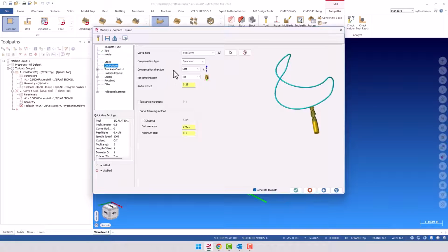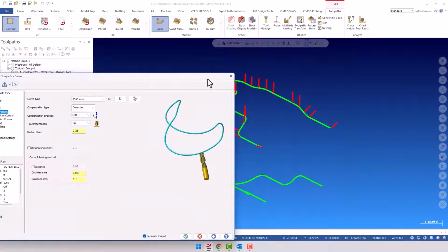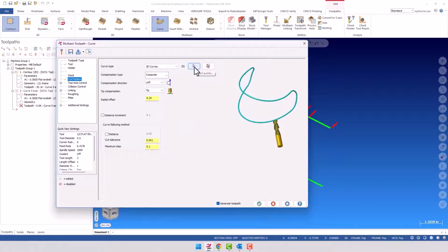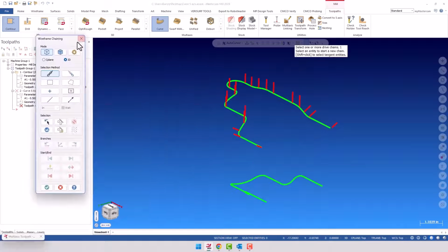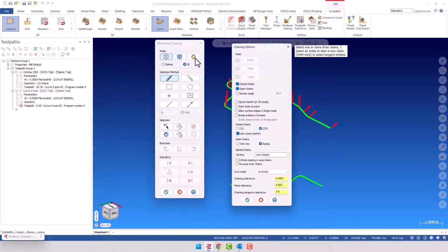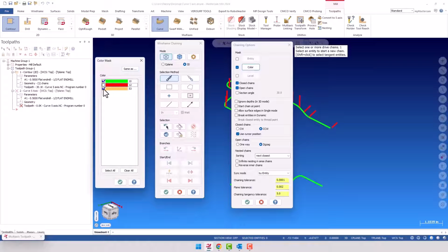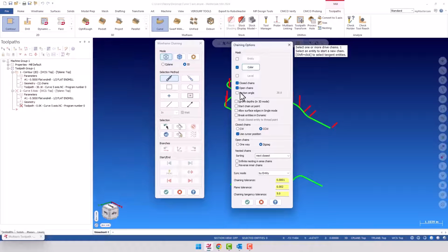So on the cut pattern, I'm going to go ahead and use the curve type through the 3D curves. We have a few selections like surface edge or all the edges or surface single edge. But again, for clarity, I'm going to use the wireframe. And what I want to do is select that bottom profile. I'm going to go ahead and say select the curves. And instead of me stopping at each of the branch points, I'm going to turn my filter on. And I want to make sure that I select only green. I'll select OK to this.